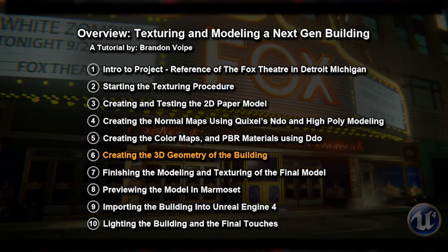In the sixth part of this lesson, we'll be creating 3D low poly geometry for the final model. I'll be showing you techniques that we used to create the original models, and then from reference we'll be making the final model. And since we've been using the grid this whole time, we'll be actually using that to make edge loops to cut the model, and then we'll be deleting those edges we don't need to lower the poly count. So let's get started.